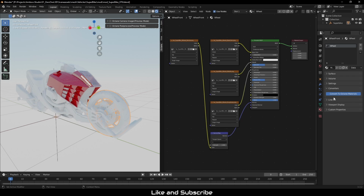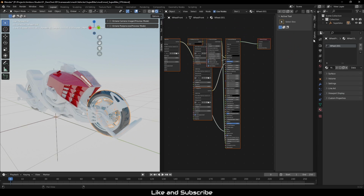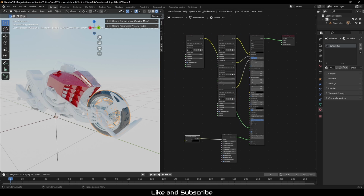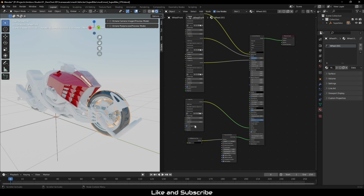Now, it's not a silver bullet. You have to keep in mind that it will only work on very basic material structures. That means if you have the albedo, the metallic, the roughness, and the normal, it'll convert fine. But if you have to feed it into other nodes, it's not going to work. And you also have to remember to set the gamma correctly after you're done converting it over.